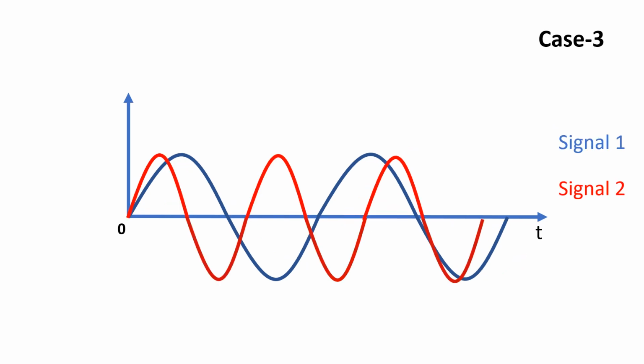In the next example, we have two signals with the same amplitude but different frequency. The addition or difference of these two signals will be non-zero, and it would be proportional to the frequency of signal 2. These examples describe the principle behind the phase discriminator or detector, which encodes phase variations between the two signals into equivalent voltage.